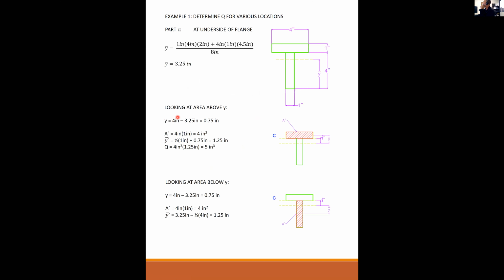B is equal to 1 inch. Go back here just a second. My shear plane is right across here, and that's 1 inch wide. That's why B is only 1 inch in this case. It's not 4 because you don't have contact across that whole 4. You only have contact between these two across this 1 inch wide shear plane. So B is equal to 1.